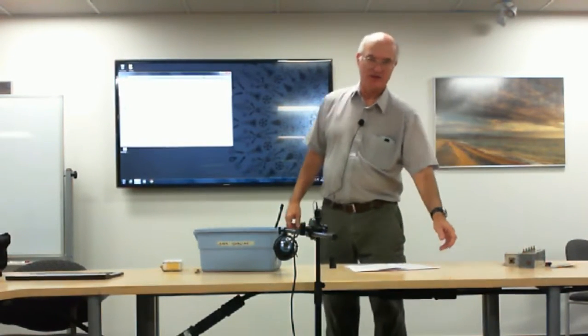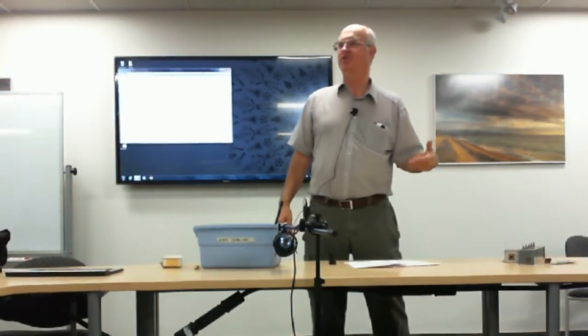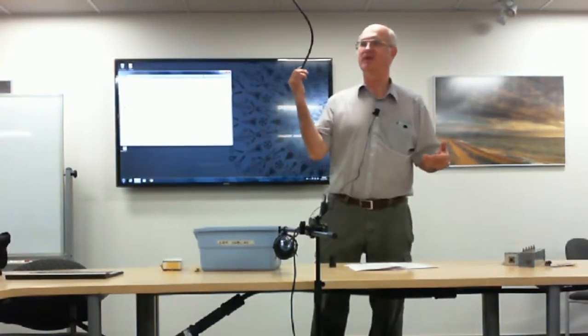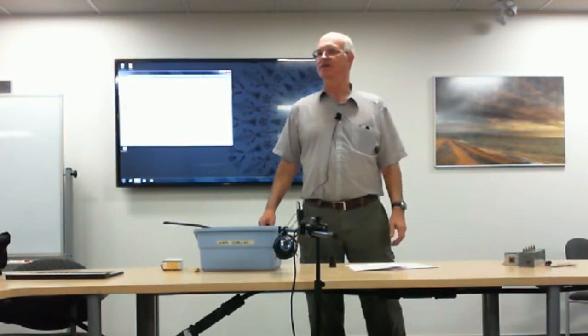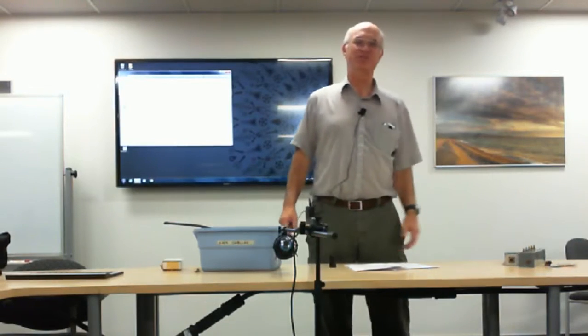Once you determine that your receiver is overloaded, there's only two ways to deal with it. You either have to desensitize your receiver, and that means losing the ability to receive the signals you want as well, or you've got to filter it out. In some cases, maybe this will do it. Maybe not. Maybe something a little more advanced. There's a wealth of information on the internet of filters and things and ideas to deal with every aspect of interference you could think of. The guys have been there, they've done it. So don't be afraid to do some research if you run into a problem.